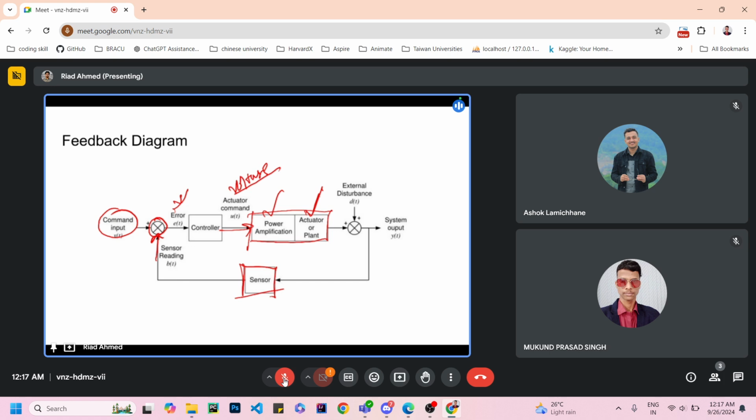But the motor you are using in your robot is not bound to 0 to 5. It can be a 12-volt motor, it can be a 24-volt motor. If you are using a 12-volt motor, that means the motor is expecting 0 as the minimum voltage and 12 as the maximum voltage. But the voltage coming from the controller is bound to 0 to 5, while the motor is expecting 0 to 12. So how can we match the expectation of the motor with the supply of the controller?